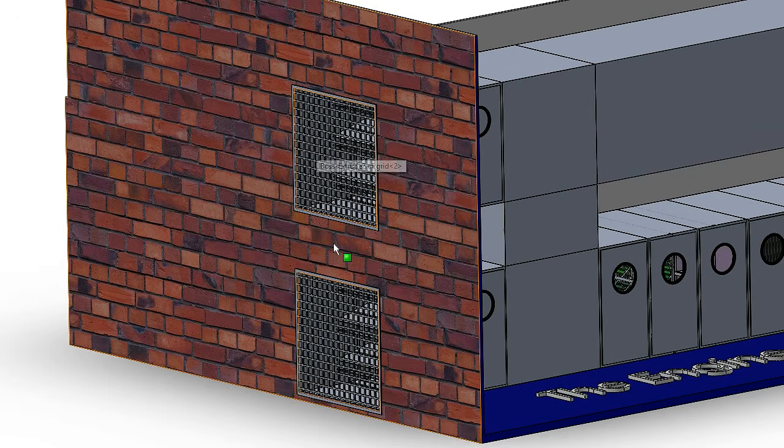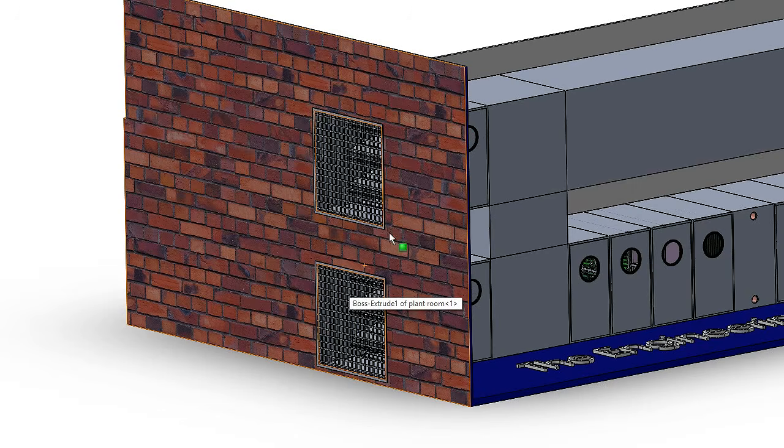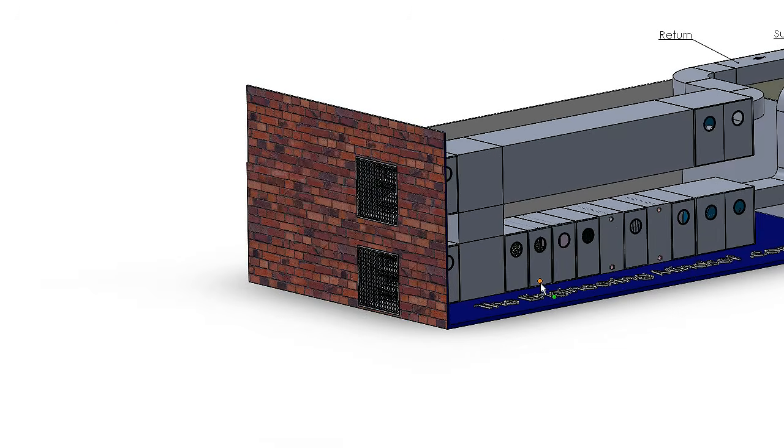It's obviously important not to have these two ducts too close together, because you'll just get recirculation. So ideally these would not be positioned so close, but for an example, and so you can see how this is working, I've left it so close. But in the real world, do not do this. Don't put it as close as that.